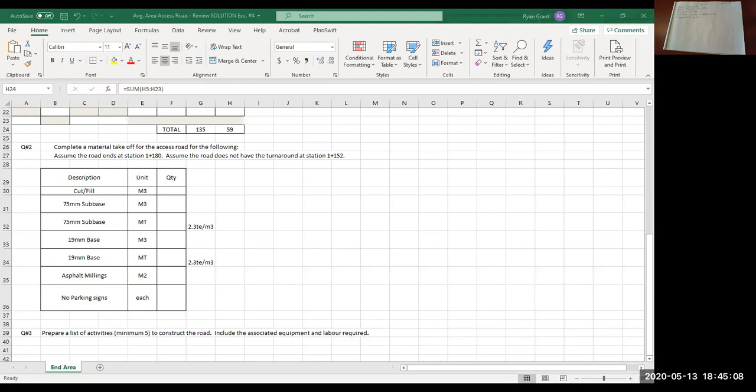So those three materials. So the fourth one, maybe for clay and silt, maybe clay is a better example. You could use a number like maybe 1.8 or 1.9 tons per cubic meter. Again, those are compacted densities. So after you've placed the fill and you've compacted it with your roller, that's what the density will be of those various materials.